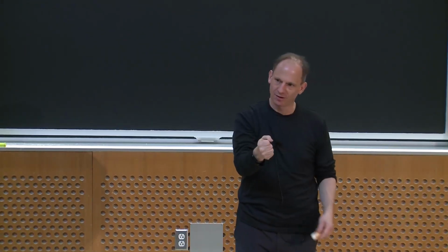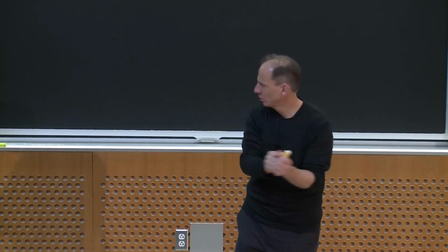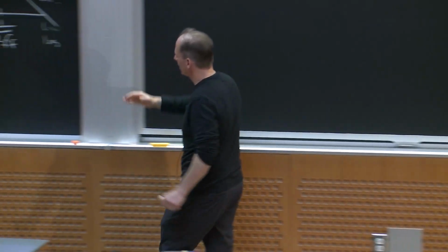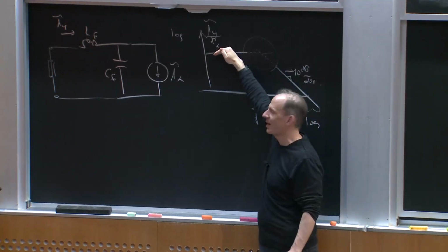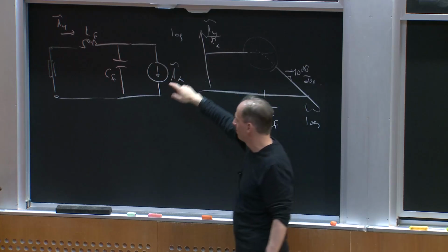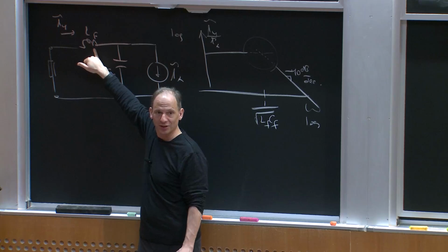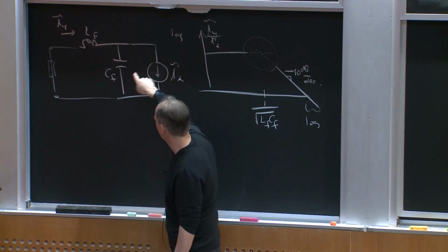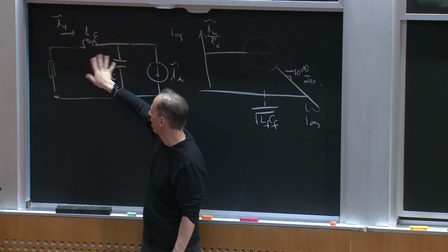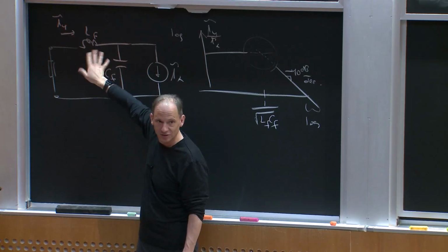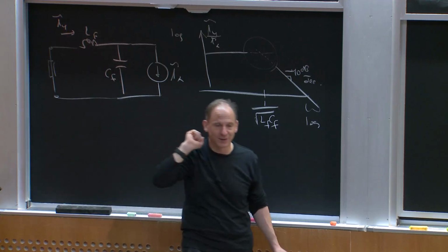I have an inductor in parallel with the capacitor at its resonant frequency. Okay? So while I get this roll off at high frequency, and I get all the current passed back at DC, basically at the resonance frequency, LF and CF look like an open circuit. Right? What's going to happen is, if I start to draw any ripple current near the resonant frequency, I'm going to get huge circulating currents in the input. And I'm going to drive a big current IY back into my input, right?